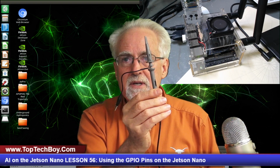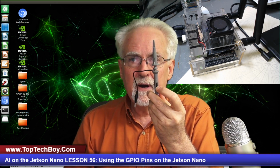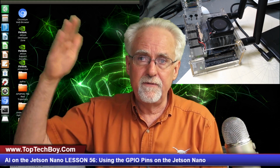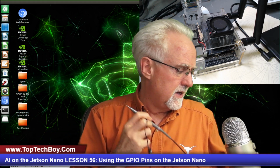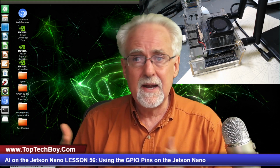Similarly, I then hooked them up to an oscilloscope with this low capacitance probe, and still it didn't work. I had to put this in the very low capacitance mode and was finally able to start seeing things on the oscilloscope. But once I understood that you've got to be concerned about the capacitive load, then I could make it work.